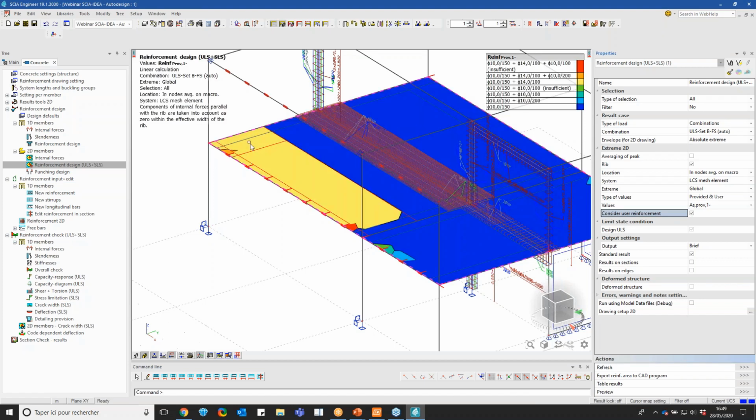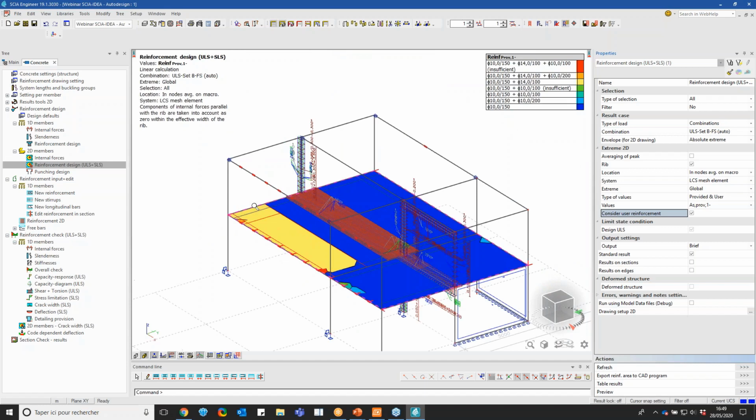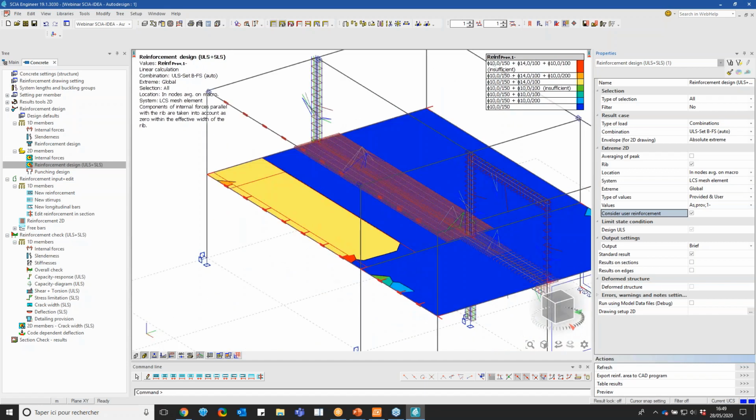So this is how you can perform this calculation, and it will show me then whether the additional rebar I added is enough, or whether I need to add, instead of 14, maybe 16 to make it work. So this is how you can perform a ULS check as well. It's really quick. We have already gone deeper in some webinars, and eventually we will come back in some trainings or webinars if you are interested as well, to have it more performant than what I show.